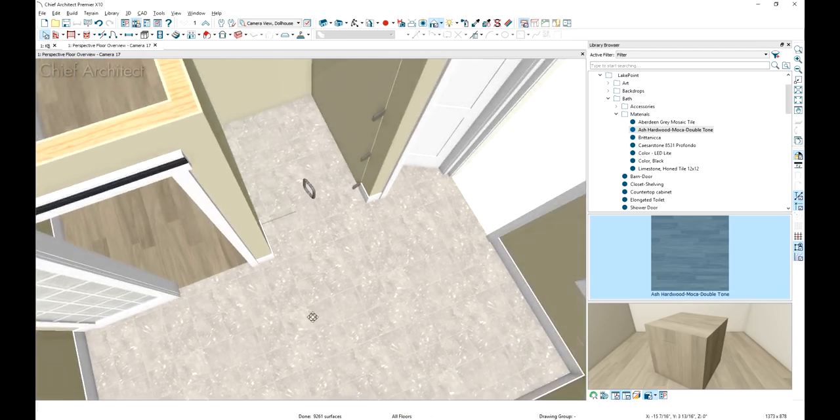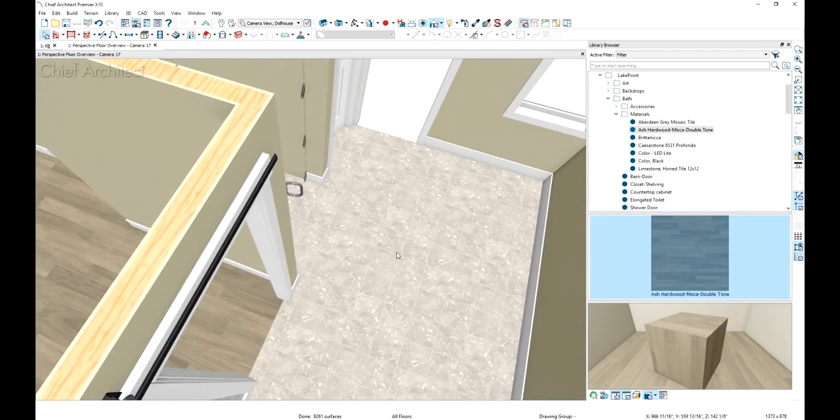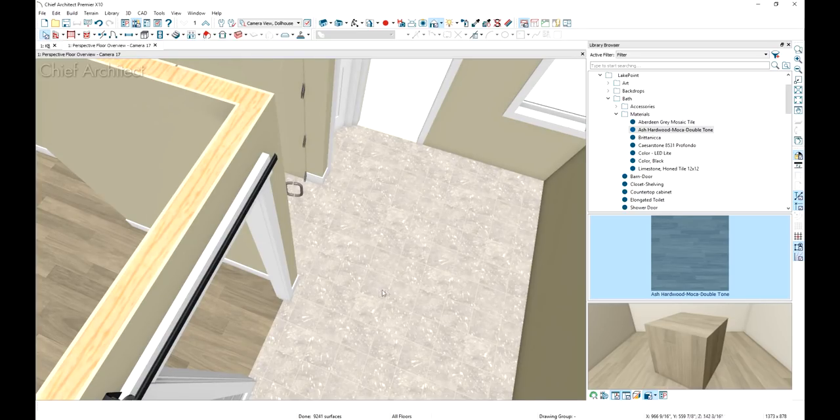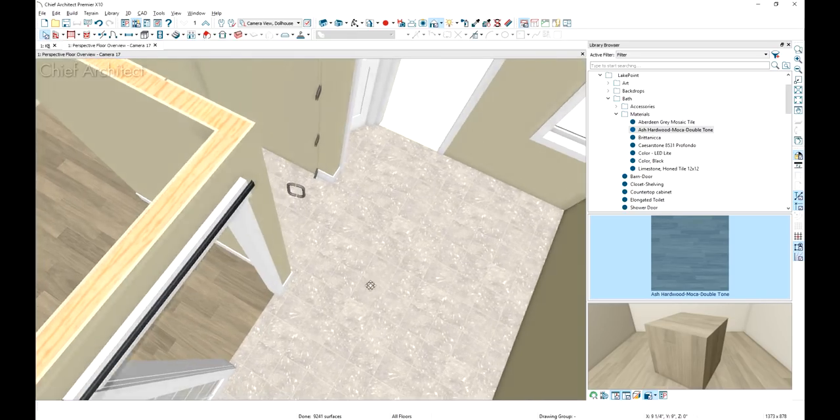Let's go ahead and rotate around. And I'm going to remove it off of this wall as well. And notice I have a segment over here. Let's just pull that over and connect it in. I have a segment because that's an exterior wall on the outside. I'm going to remove the molding off of this wall, and I'm also going to remove it off of this wall because that's going to become our cabinet wall, and I want to have more control over it.